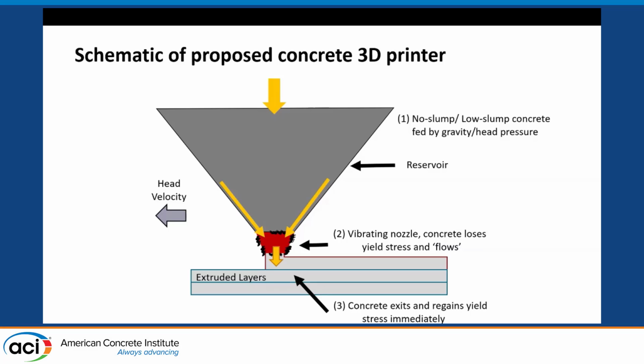Second, because of the high yield stresses, I calculated for my density and for the yield stress I was getting that each layer could be 8 inches tall without collapsing. And I don't have to wait between layers, so this will help reduce the number of layers, and there are no cold joints formed as well. Compared with how we are 3D printing now in general, we are in millimeter scales. With something like this, we could have concrete so stiff that you could have 8 inches.